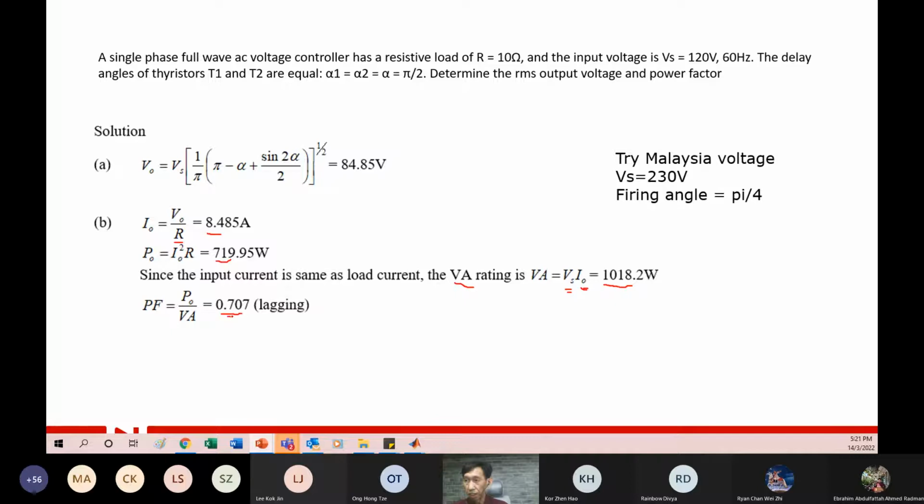You can see that when you do that, it immediately affects your power factor. So why is there not so much concern when you use it in your house? I said for single phase LV, TNB actually does not really look into this power factor issue. But in a three-phase system, if your house is a bungalow usually, or a shop lot, shop houses, where you are taking three-phase, then TNB will charge you a penalty, because TNB will start to charge you if your power factor is lower than 0.85.